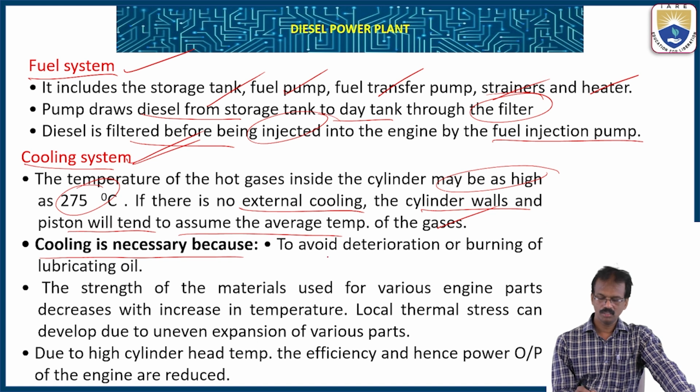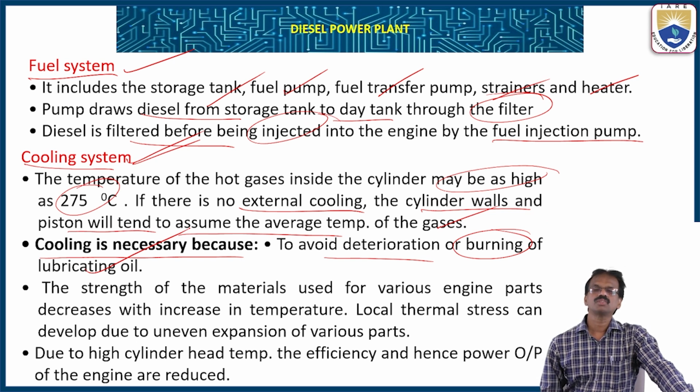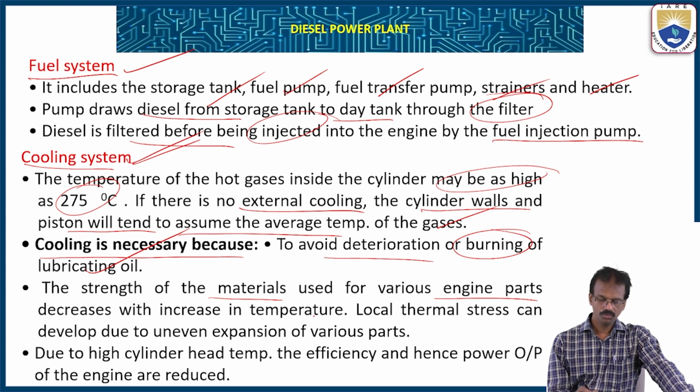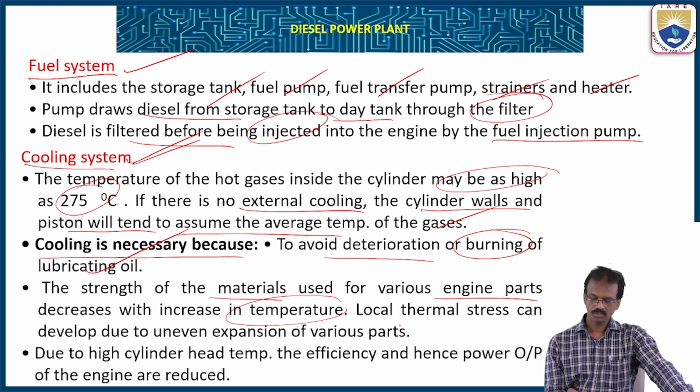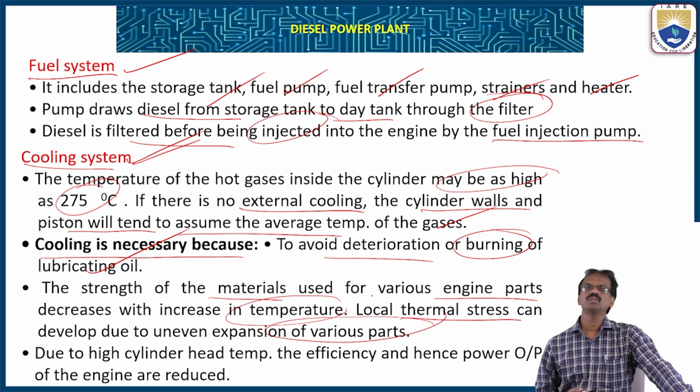So cooling is necessary to avoid deterioration or burning of the lubricating oil. Next, the strength of material will be decreased for the various engine parts due to the high temperature. Increasing temperature means that hardness will be decreased. Automatically, wear rate will be increased. Next, local thermal stress can be developed due to uneven expansion of various parts. So, due to the high temperature, the parts will be expanded.